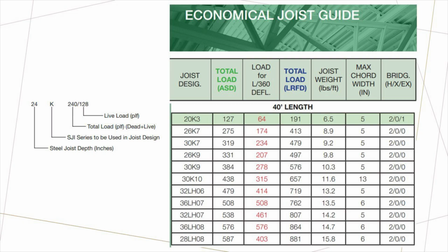The roof framing system begins with the roof deck, which must be checked for the allowable load capacity, which is based on the maximum span between the supports, or in this case, joists. Loads from the deck are transferred into the joists, which are typically delegated design elements.